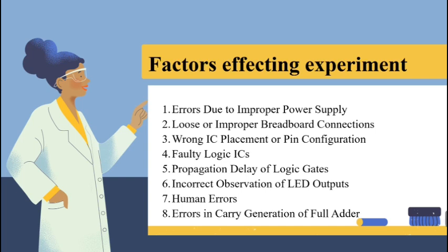The eighth one, the errors in carry generation of full adder. The full adder includes an additional carry input compared to the half adder. Because of this, incorrect carry input connections may produce wrong results. Students may forget to change the carry input during the truth table verification. Intermediate carry signals may confuse the final carry output.